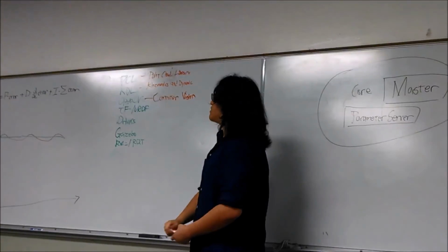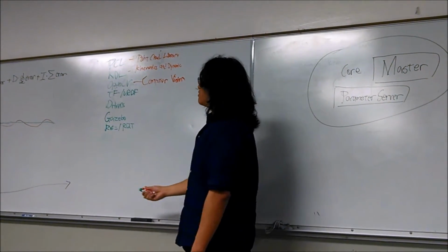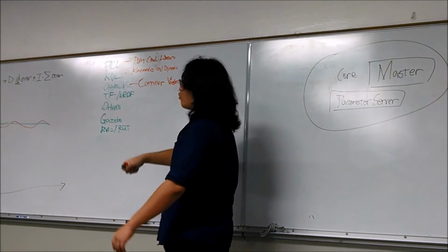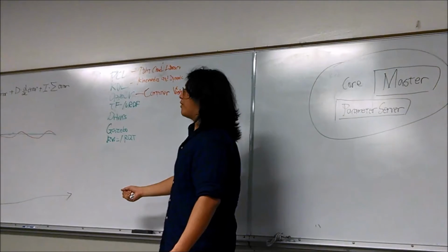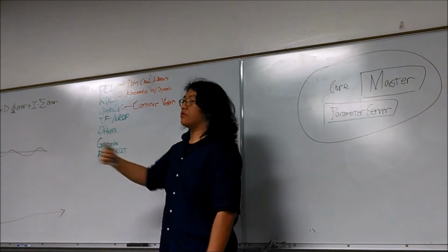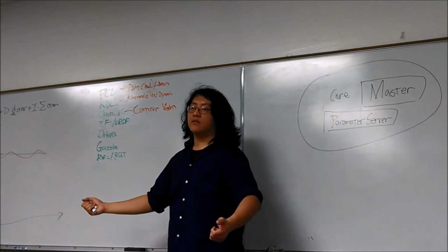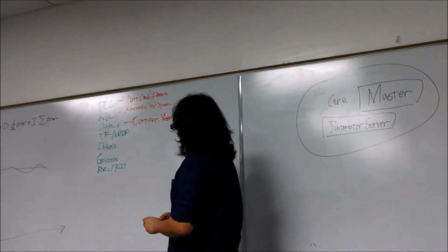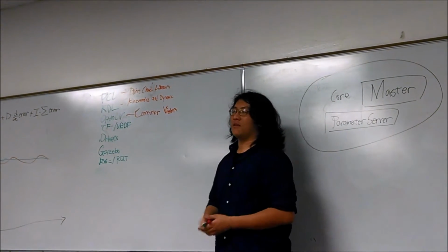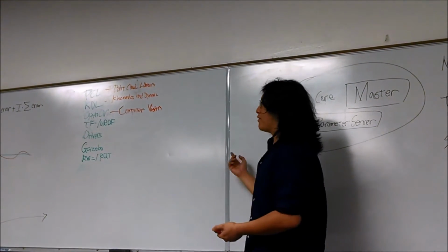And what you'll have is nodes that you can run that will broadcast to your TF where my frames are, well, where your fixed frames are, or given that and the current joint locations, what the current state of the body is. ROS also contains drivers for anything anyone commonly uses, mostly USB devices or Ethernet devices that you'll plug into a computer that'll be running ROS.